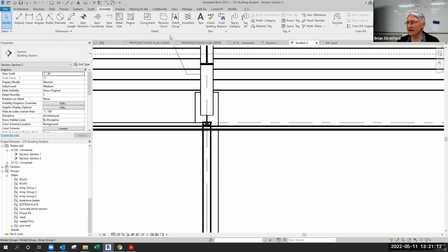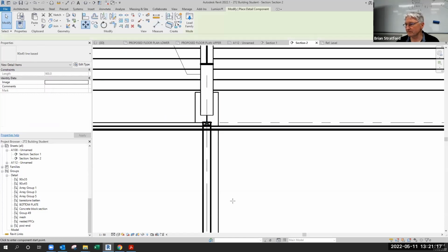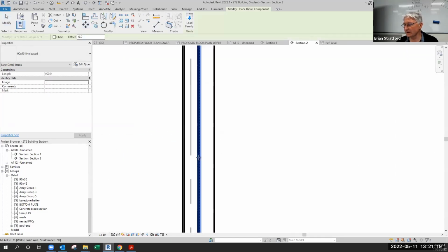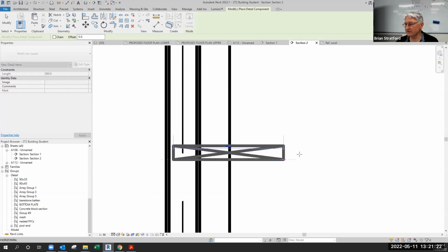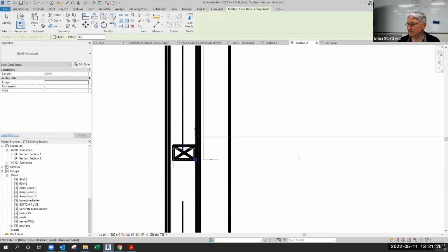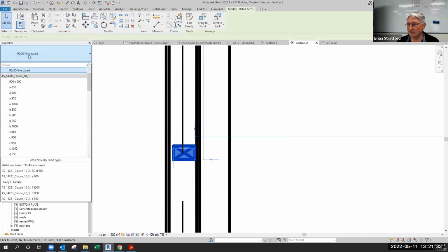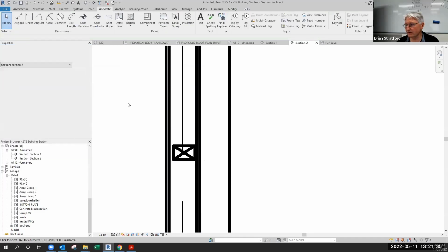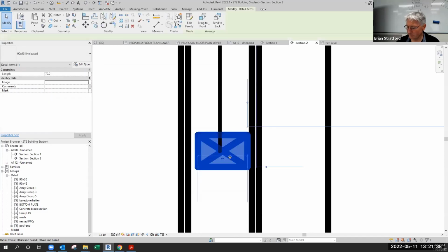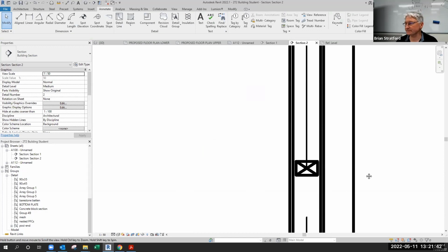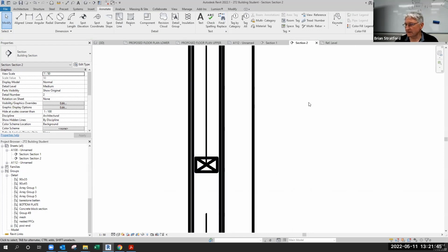Annotate, and we can go across to component. And I've got a nogging that I know is 70 millimeters across here. That's there. This is our 90 by 45 line based, and in amongst that we can create two families, a 45 and a 35, because the nogging would be probably a 70 by 35 in a traditional residential sense anyway. So that seemed to work so far.